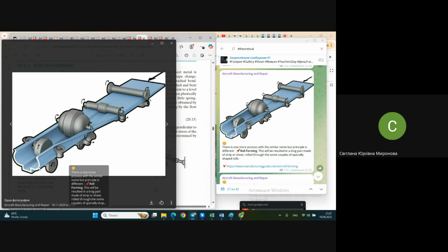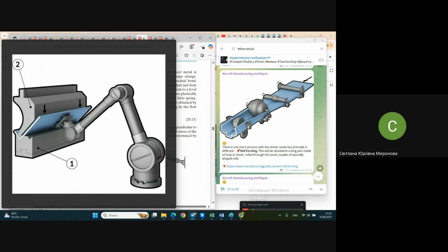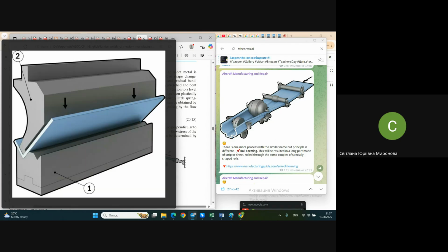In contrast to the bending machine, let's compare here the scheme of a bending machine. The bending machine may work only along one line, this V bending. It may work with more primitive shapes, let's say, and probably it will not create such a shape with some half cylinder elements and so on, or at least there will be a significant spring back effect here.